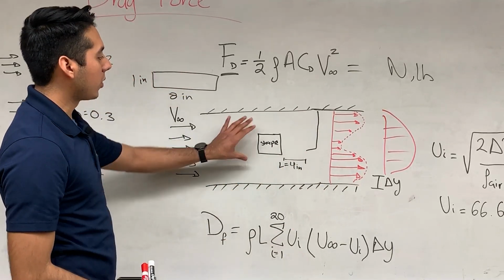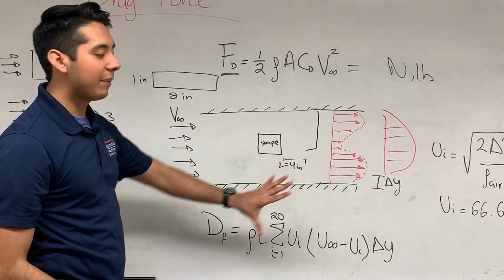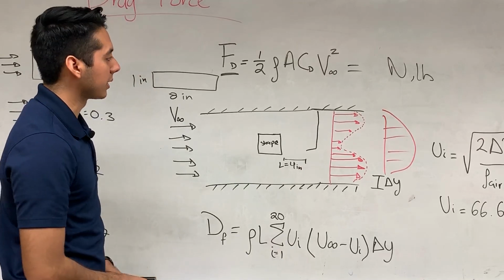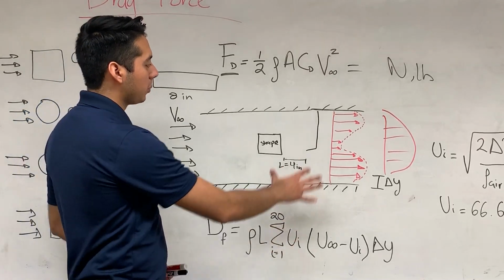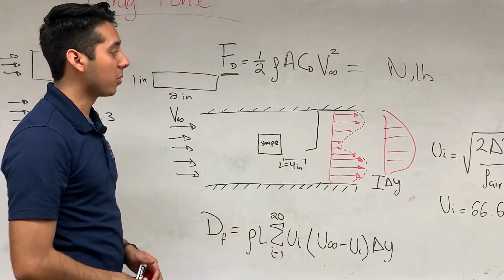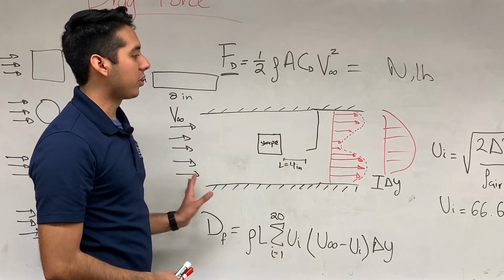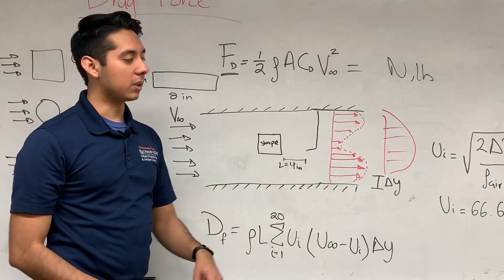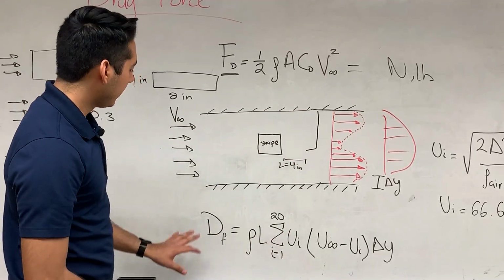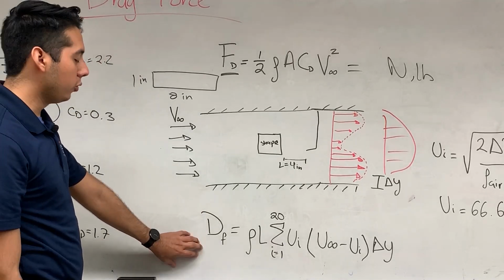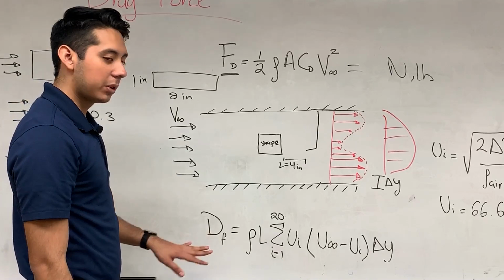It's just that when you have a different figure, you may have slightly different increase or decrease in some of the sections. So you have to make your graph of these shapes in your notebook and in your report, of the velocity profile versus the distance in the duct, just like we did with wind tunnel 2. And then we're going to be calculating also the drag force using equation 2 over here. The same equation should use same units.